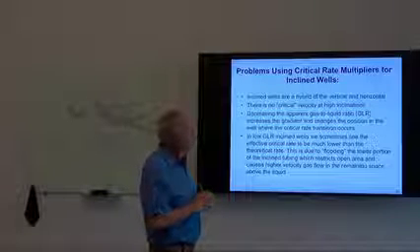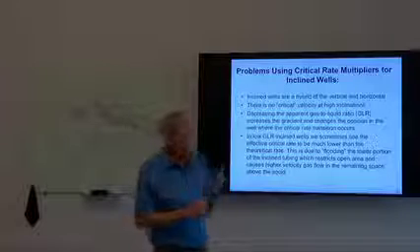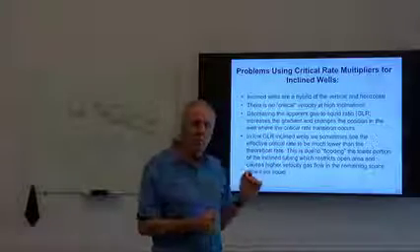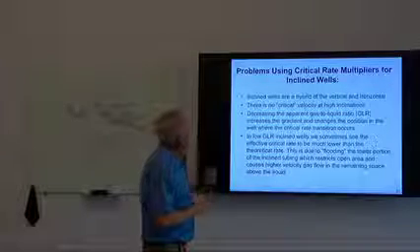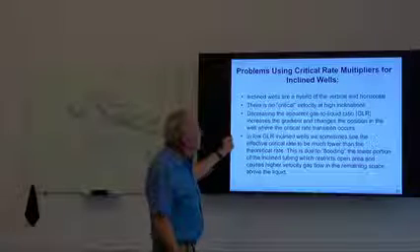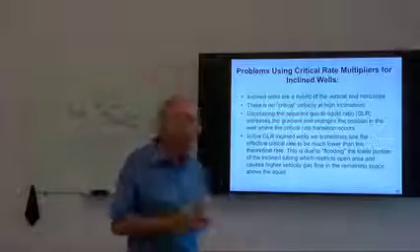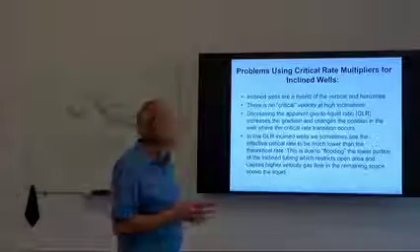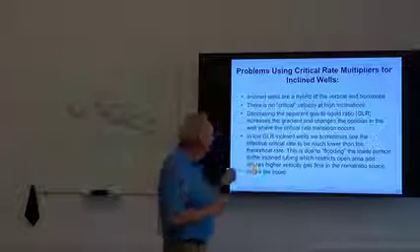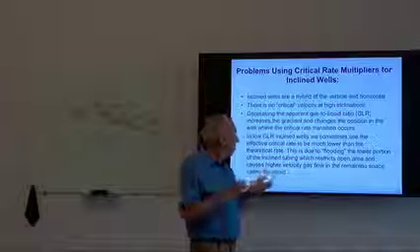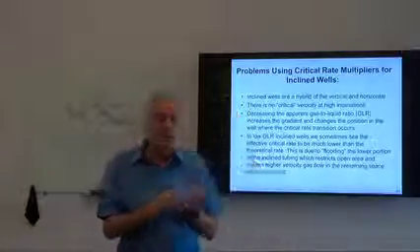And decreasing the gas to liquid ratio increases the gradient, and changes the position in the well where the transition takes place. We looked at that a number of different ways earlier. And in low GLR wells especially, we see the effective critical rate, that is the rate at which we actually begin to accumulate liquids, being much lower than what the theoretical rate is. So we're flooding the lower portion of the tubing, restricting open area, causing high gas velocity over the remaining space above the liquid, but that isn't sufficient to keep the liquid moving up the well.